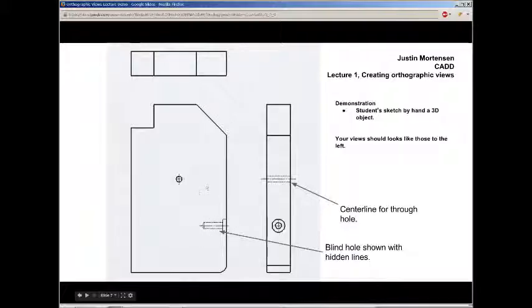Otherwise, you cannot see that blind hole with the counterbore in this front view. It's just not visible. And also this round here. If we take that and flip it to the side, now we're looking at the side view, two-dimensional only. Here's that chamfer, and notice the edge of the chamfer is lined up perfectly with this side view. There's the edge, and here we see that whole edge coming across, and that's something we'd have to draw. Likewise, we have the hidden lines for the through hole here.